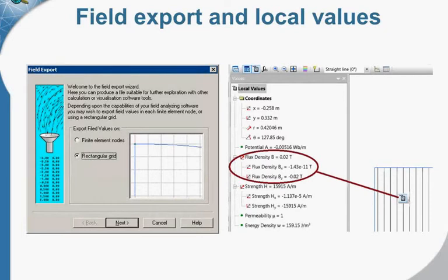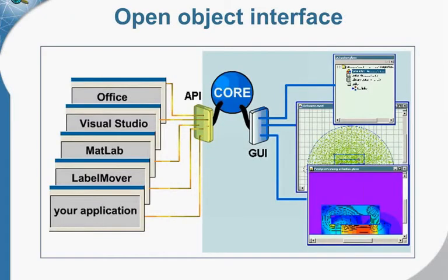Extraction of the field parameters may be performed for some region or even for the full finite element model, or on demand for specific point where the particle is located in given moment of time. For automatic extraction of on-demand field results, we have special technology called ActiveField. ActiveField is an object-oriented application programming interface to QuickField core functions.